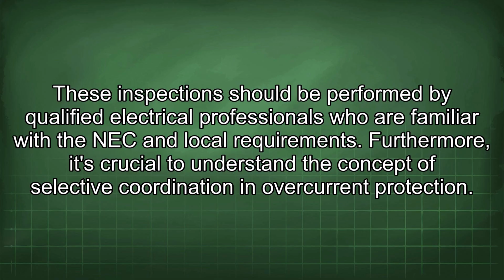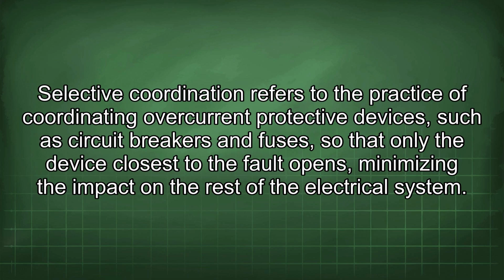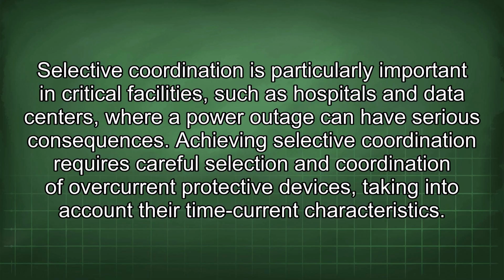Furthermore, it's crucial to understand the concept of selective coordination in overcurrent protection. Selective coordination refers to the practice of coordinating overcurrent protective devices, such as circuit breakers and fuses, so that only the device closest to the fault opens, minimizing the impact on the rest of the electrical system. Selective coordination is particularly important to critical facilities such as hospitals and data centers, where a power outage can have serious consequences. Achieving selective coordination requires careful selection and coordination of overcurrent protective devices, taking into account their time current characteristics.